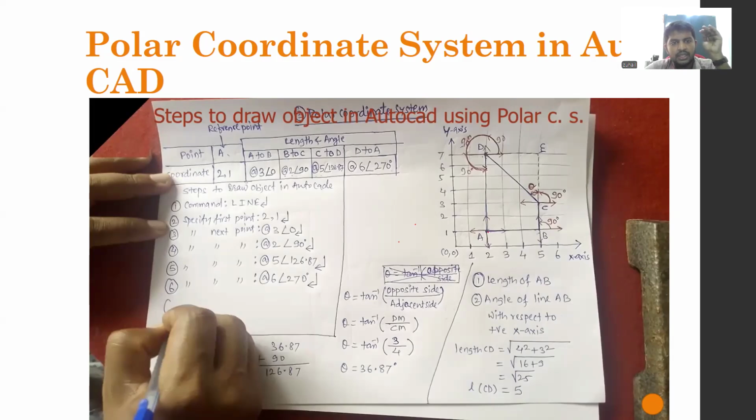This is the way of writing the command. Step to draw the object in AutoCAD: command L, enter. Then specify the first point as 2, 1. Then for the next point, at 3 less than 0, enter. So this is the way you have to write.